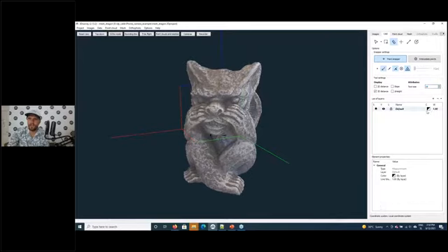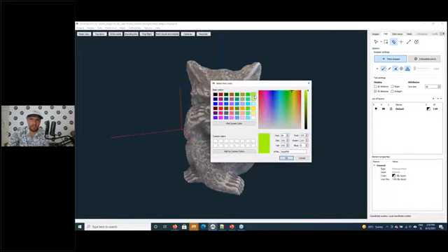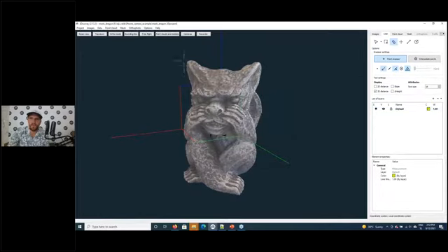Make it bigger, make the measurement green. Go to measure. Like that, it should be about 6.7 centimeters big. Because in the beginning we inputted centimeters instead of meters, so everything is actually in centimeters, not meters. So this means that the statue is 6 centimeters wide. And this is how you would calibrate your phone camera.